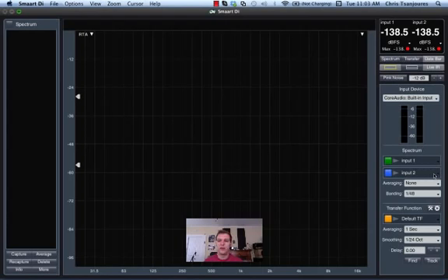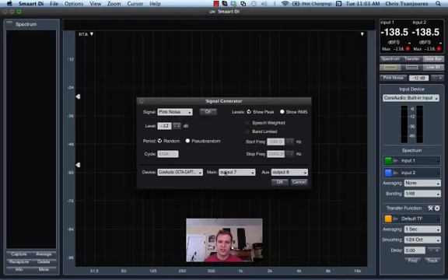So the way I have my I/O configured is I'm going to be using the pink noise generator, and I have the device OctaCapture selected, and then main output 7 and 8. Now 7 is going to a loopback, which is going right to input 2 of the interface, and output 8 is going to an equalizer, which is in front of a speaker that we'll be measuring later.